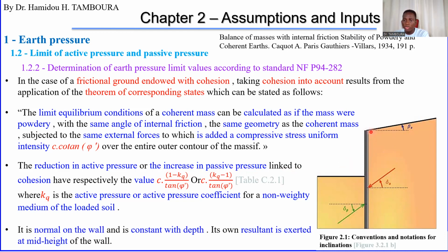If you take, for example, the earth pressure, it is like this triangle, or even the water pressure is like this. But this contribution of the cohesion is just like this, uniform when you go deep with the depth.